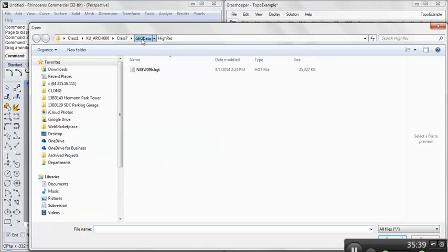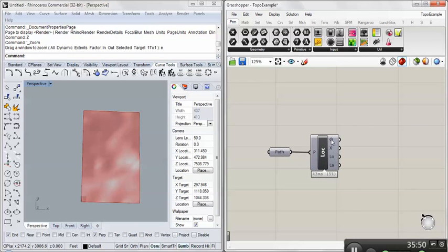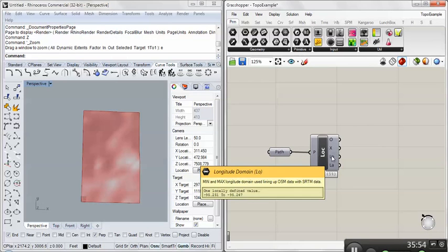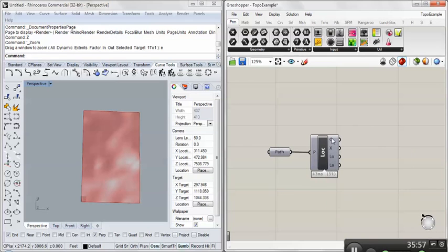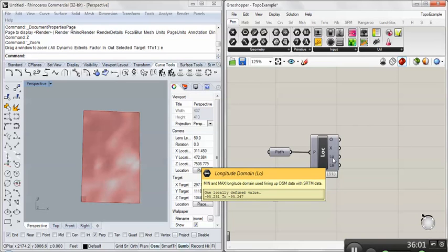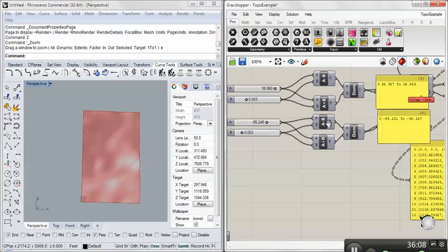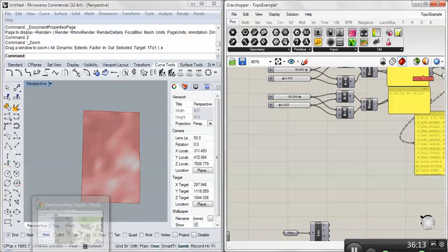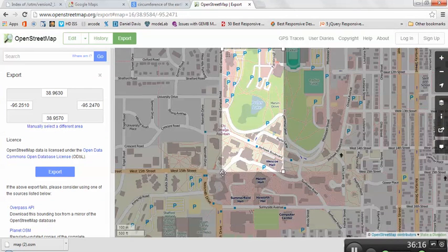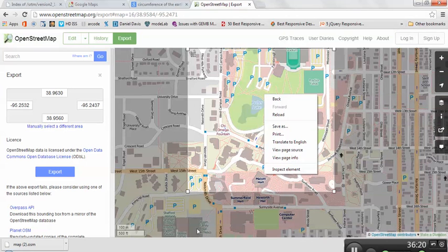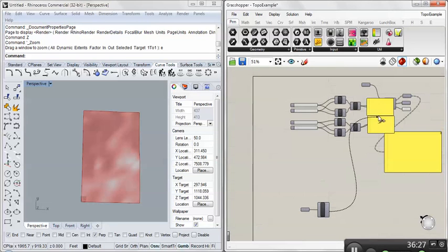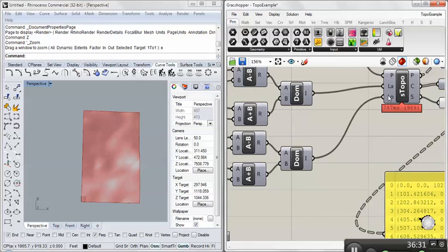The other data set is still under the geodata OSM. Map 2 OSM was what I sent to you earlier. Go ahead and drag that there, and now I should have items filled out here. One thing you can see, it brought across the longitude and the latitude that we had typed. So later you can either manually set it like this, where you define what your area is, or you can go ahead and just go to Street Maps, find your site, drag this for how much context you want. And you can drag those up, and that should work exactly the same.